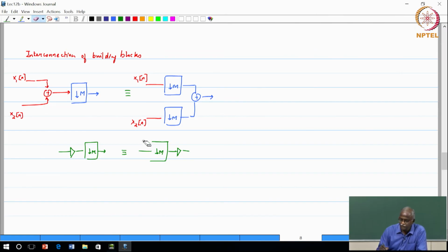Now, is there a difference between these two? You may say nothing, because in one case you scale and then multiply, and in the other you downscale first. Actually, what is the downsampler going to do? It is going to throw away samples. In that case, why multiply? Throw away the samples, only keep the samples that you are going to keep, and then do the computation. Why waste effort multiplying and obtaining results? So, yes, this would be the preferred option. There are several times when you may want to optimize your structure and therefore do things a little bit differently.